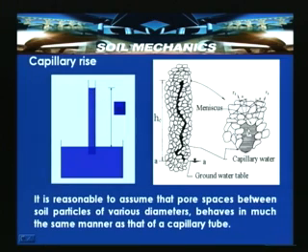It has an upward pull, which is resisted by the self-weight of the water column within the glass tube. Similarly, here also, water is pulled against gravity above the groundwater table and is resisted by the self-weight of the water within that column.